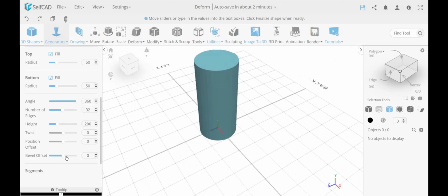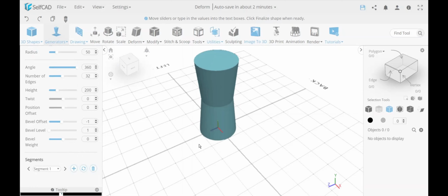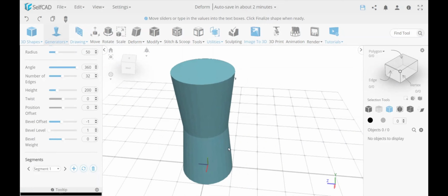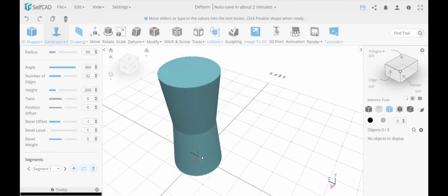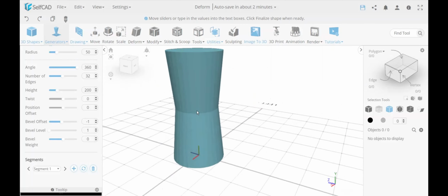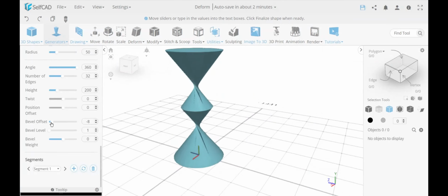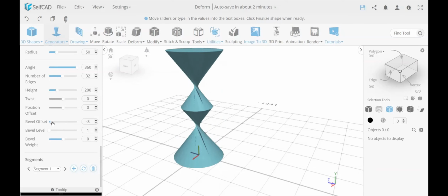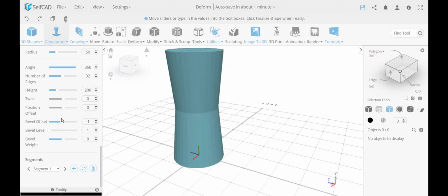Now what I'm going to do is add a bevel, but a negative bevel, so -1. And if you see what's happening over here, this is important because I'm going to explain the same concept using round object soon. The bevel is simply making an indentation. It adds a split, and it gives it a smaller size based on the amount I'm beveling. I can bevel it this way until it starts self-intersecting. Actually, this will create a non-manifold shape, but until they start self-intersecting, I can make it as much as I want. So let's say 1 is fine for now.